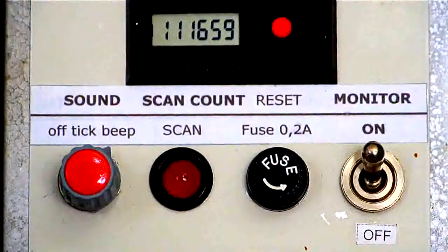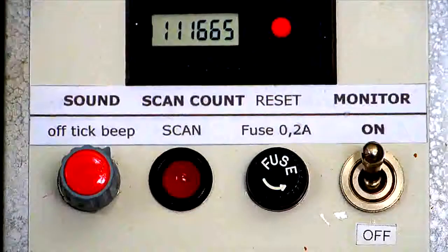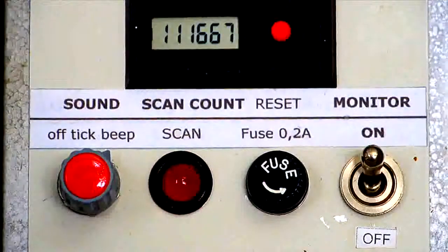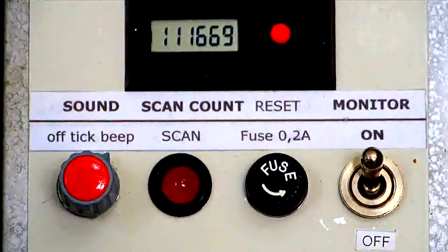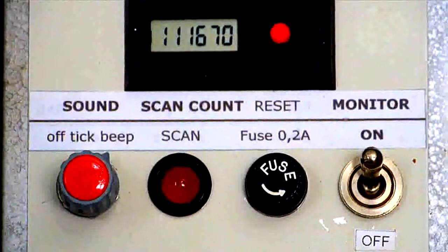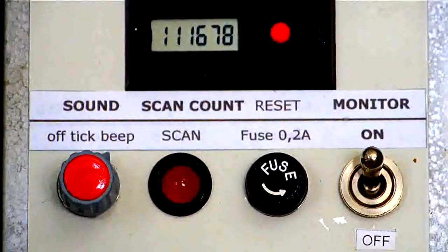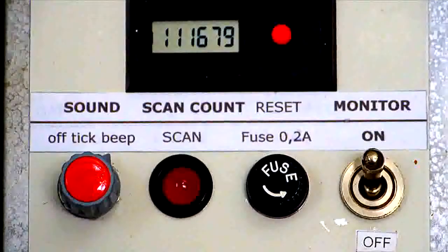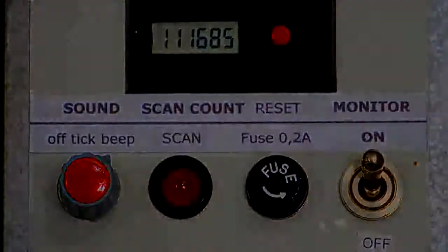The sound switch is put to the beep function. These pulses arriving at the CPA sensor module permanently are indicated here by a red LED, and counted by the digital counter. The CPA system is very sensitive, and indicates the very weak energy impulses of the so-called natural background radiation, which exists everywhere in the world, in diverse intensity. It produces irregular pulses, between roughly 50 to 1000 or more pulses per hour, depending on the geographical position. For normal silent operation of the CPA system, the sound should be switched off.